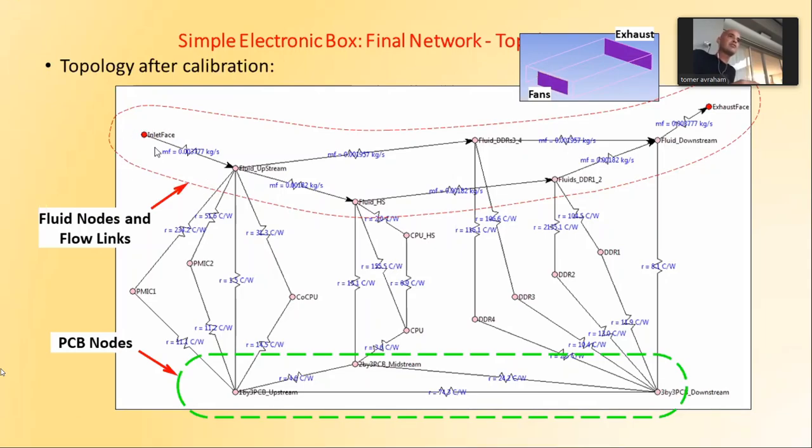But there's no problem to find a pressure drop inside the area. You just run the CFD and check the pressure drop. You'll probably get a system pressure drop of kind of parabola, a steep parabola if there are many disturbances to the flow, flat parabola if it's kind of an open system, but that's it.